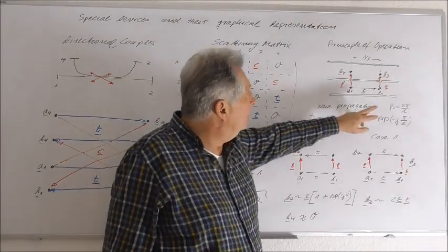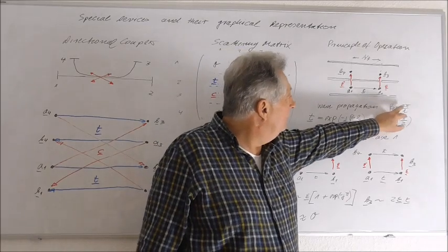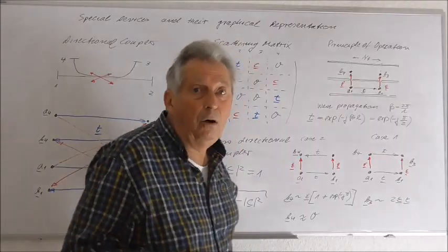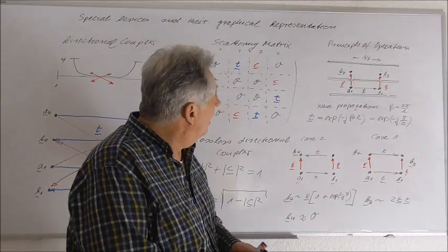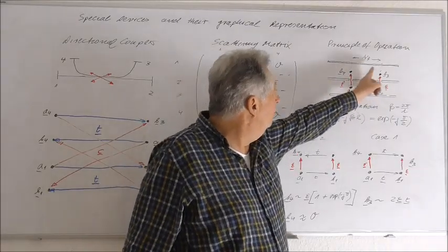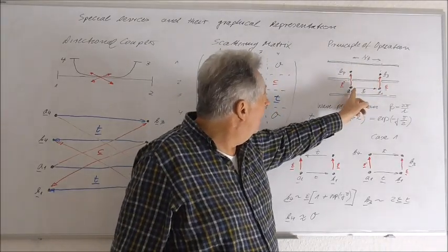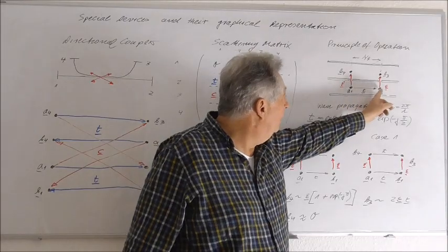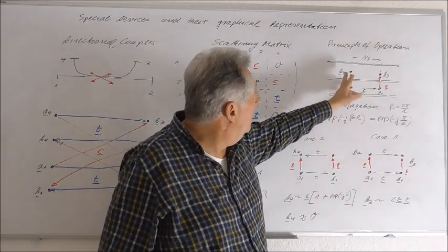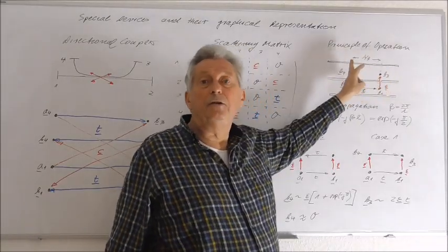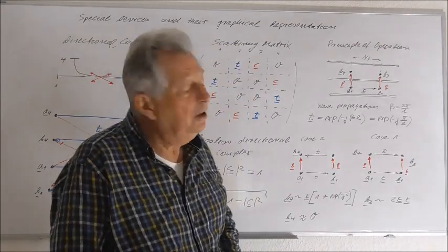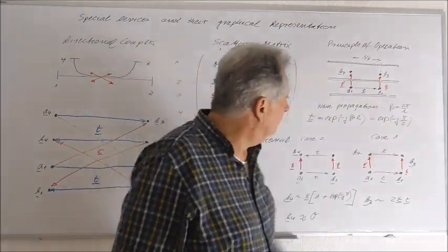As you know, wave propagation is described by beta equals 2 pi over lambda, where lambda means the wavelength in our waveguide. And so for the transmission coefficient, I inserted here some wave amplitudes, and we will have a transmission from here to here, which will be essentially e to the minus j beta L, where L is the distance of the two holes, and this will result in a phase shift of 90 degrees.